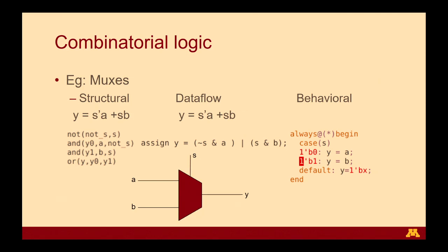If you're testing a 2-bit value, you should have 4 conditions tested. This is an important characteristic because when we talk about flip-flops and other designs, we'll go over how the tools differentiate between combinatorial logic and actual flip-flop logic.